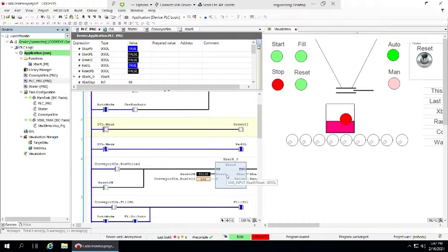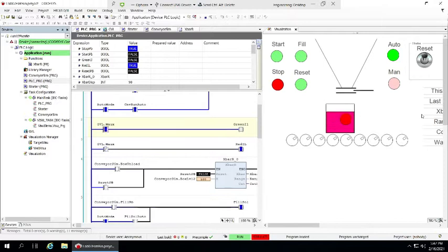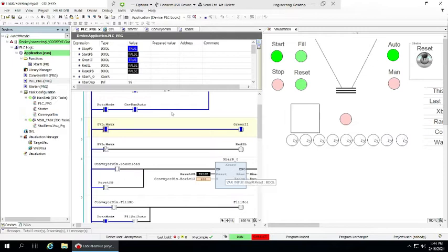I have a piece of structured code here. So this is ladder logic. This is structured code, and so every time you do a box unload, which is a signal that the box is going off the end of the conveyor, so do some other handling, then I run this little equation, and that is over here in area X bar.